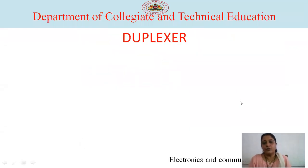Now, moving on to the next circuit, that is the duplexer circuit. We have already come across the word duplexer in the basic block diagram of the radar. What is the duplexer? If we are using the same antenna for transmission and reception, then to protect the sensitive receiver from the high voltages or high power of the transmitter section, we use a circuit called the duplexer.